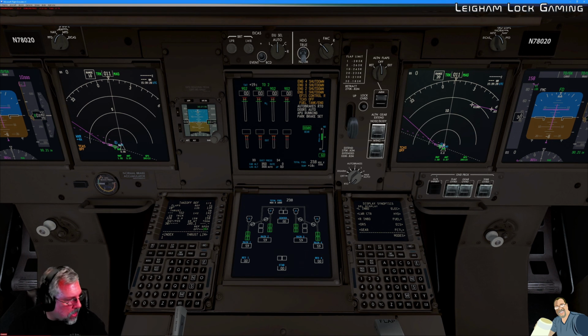So up top here, I guess I should have pointed this out first, what we're addressing by looking at this information is there's a warning for fuel tank / engine. We need to address this warning by looking at these numbers and turning off the crossfeed for 1, that's this valve here, and the crossfeed for 4 will resolve this warning message.